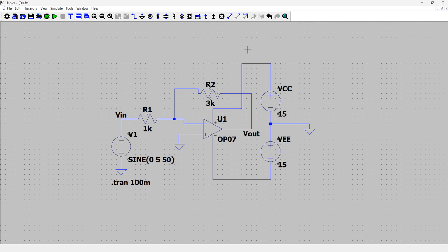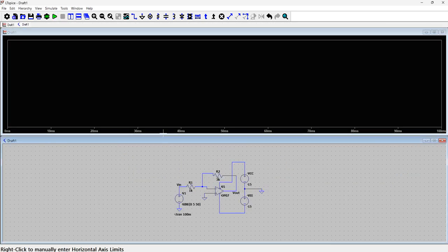As you can see, we have labeled all the components over here. So for simulating it, I have to click on this. Yes. Now after clicking on this run, we have a window, a terminal, where we can see the output. For that, I have to go to the V input terminal that I have labeled.